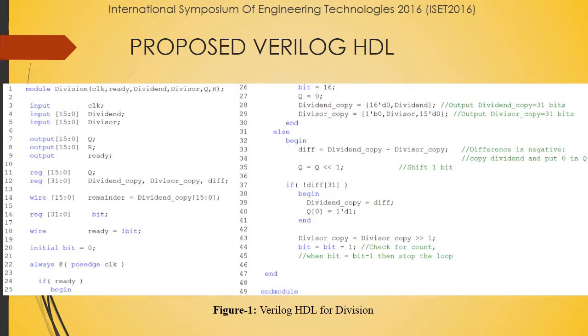In this paper, the Verilog HDL codes for division are generated and simulated using Xilinx 14.4 ISE ISim. The Verilog HDL code is broken down into modules which deal with the division of a 16-bit dividend and 16-bit divisor. We choose the non-restoring algorithm because it is simple to implement since it requires a basic adder or subtractor operation and the shifting process, which is to the left or right in each stage of calculation. Hence, it does not involve other hardware components such as multipliers and multiplexers.